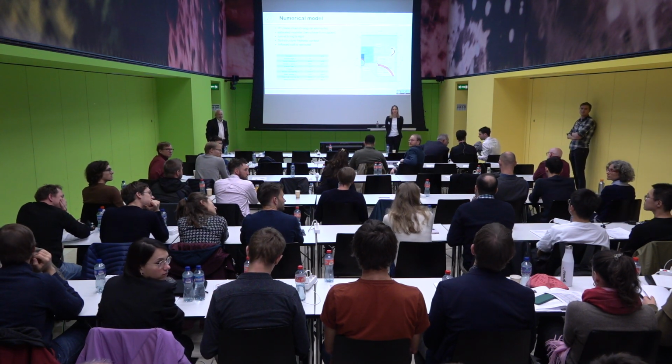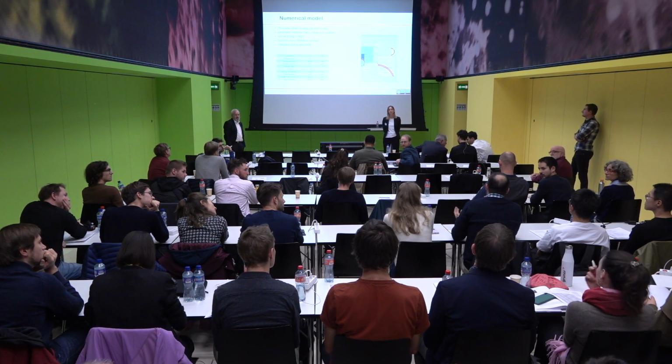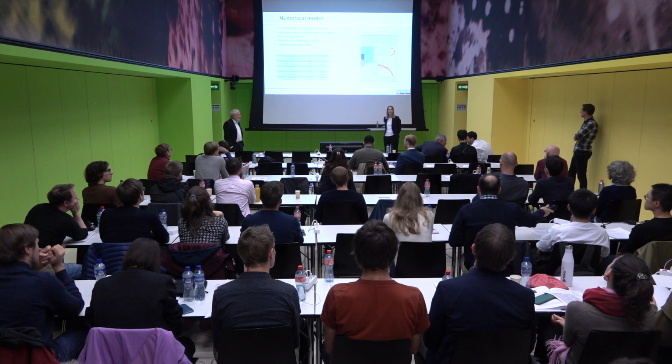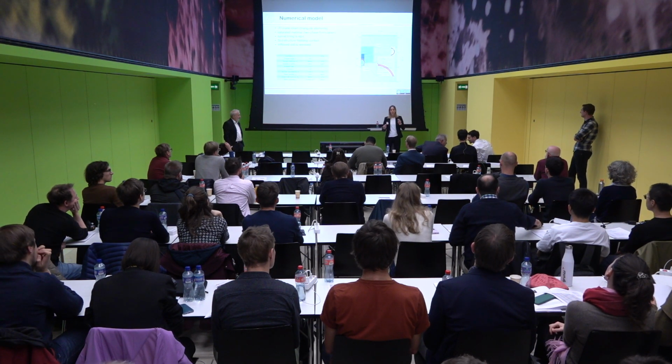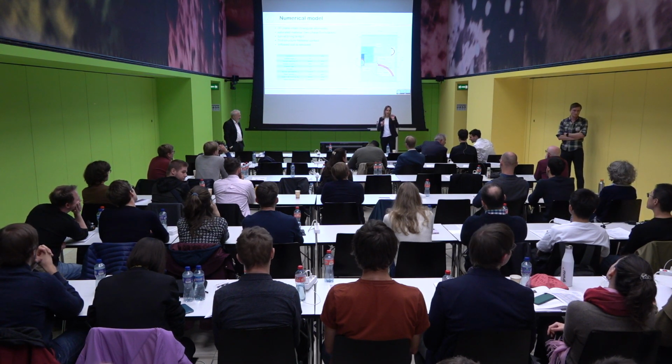Thank you very much for the presentation. Maybe a short question related to the discretization, because it's a discretization method. Is there any general rule for how you choose the size of your discretization? Yes, good question. You have two levels of discretization. One is the size of the mesh, the elements, and the other one is the number of material points. The size of the mesh has the same effect as in FEM. So the mesh that you would use for your FEM problem is good also for MPM. Remember that we have linear elements, which means it should be a little bit smaller in general, but it's comparable.